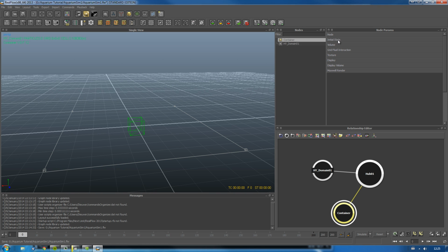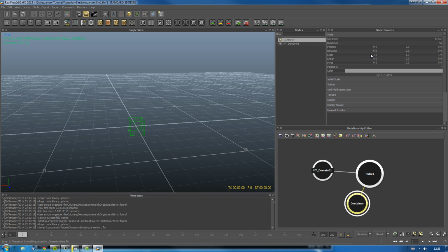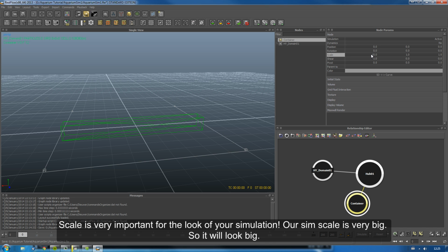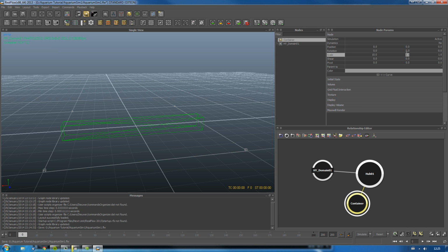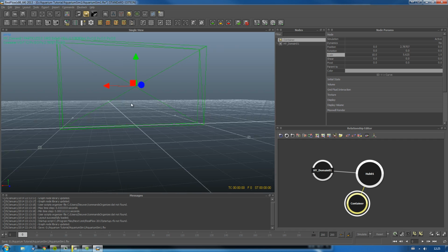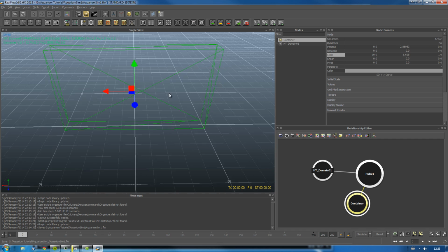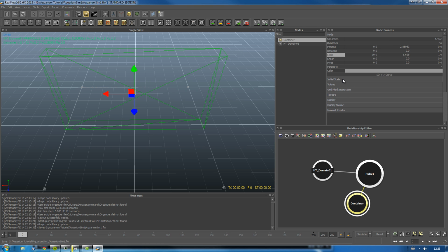And because we want to fill the screen, and the screen is going to be 16 by 9 aspect ratio, then I'm going to give the cube dimensions that are also 16 by 9. The dimensions in Realflow by default are in meters, I think. So the box is going to be 10 meters wide. It's quite large. I'm going to make it 5.625 meters high and 1 meter deep. Move it just to the base a little bit. There we go. It's perfect.